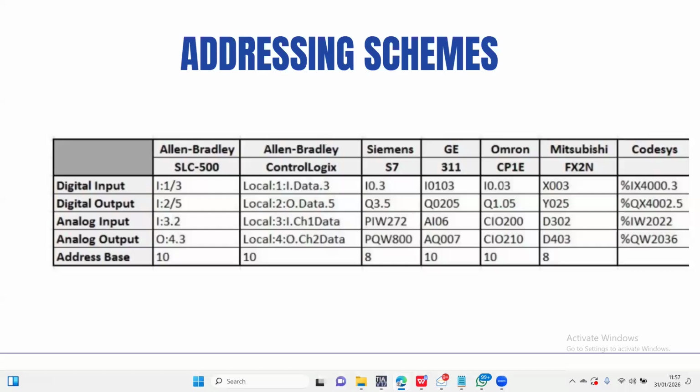It's going to take too much time for me to go into, but for transmitters, you can have 4 to 20 milliamps, you can have 0 to 10 volts. You have Profibus, AS-i, and there are some transmitters that support Modbus RTU. There are many, many ways you can pull signals. There's Profibus PA, there's Foundation Fieldbus. Communication is a completely different topic that we can spend a lot of time going into.